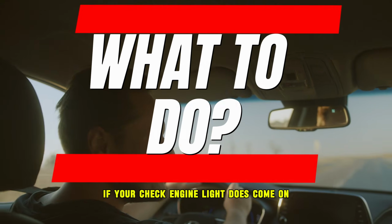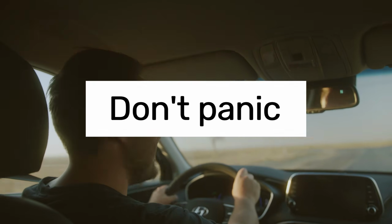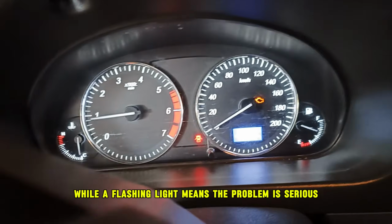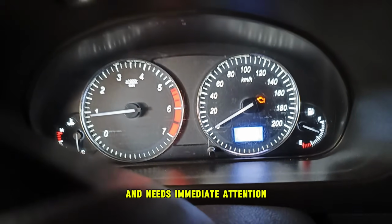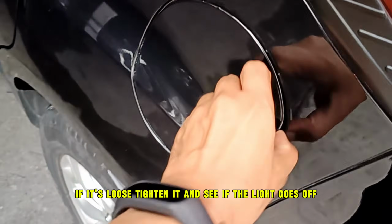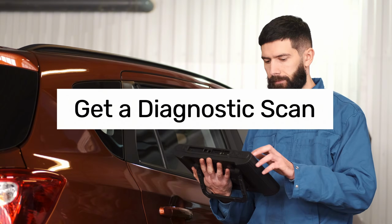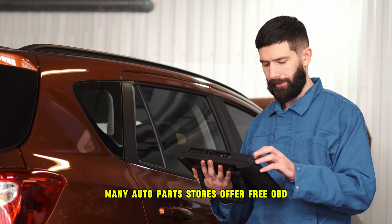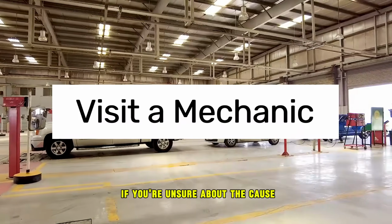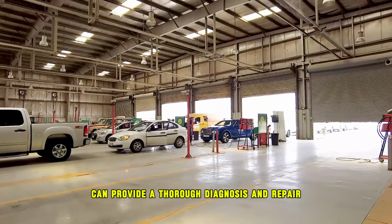So, what should you do if your check engine light does come on? Here's a step-by-step guide. Don't panic. A steady light usually indicates a less urgent issue, while a flashing light means the problem is serious and needs immediate attention. Check your gas cap. If it's loose, tighten it and see if the light goes off after a few drives. Get a diagnostic scan. Many auto parts stores offer free OBD scans that can identify the problem. Visit a mechanic. If you're unsure about the cause or the light stays on, a professional can provide a thorough diagnosis and repair.